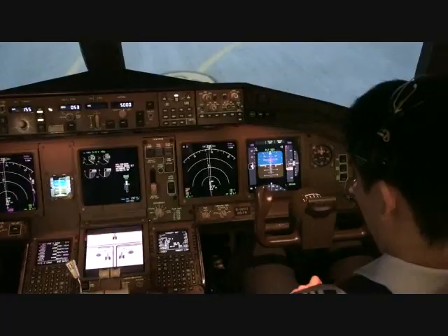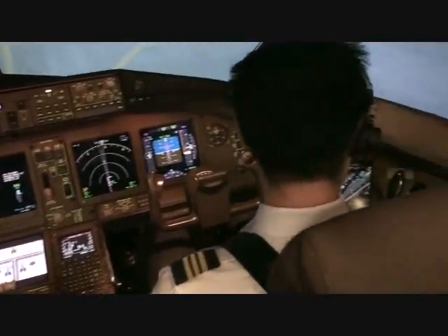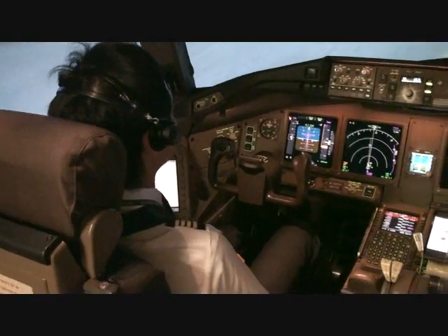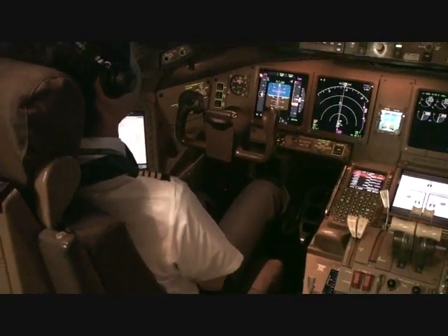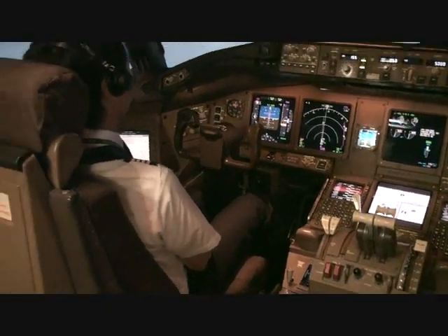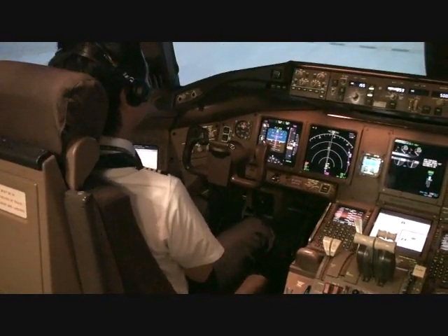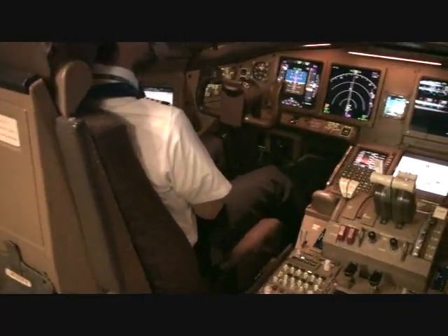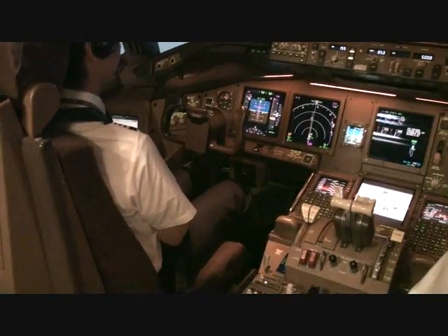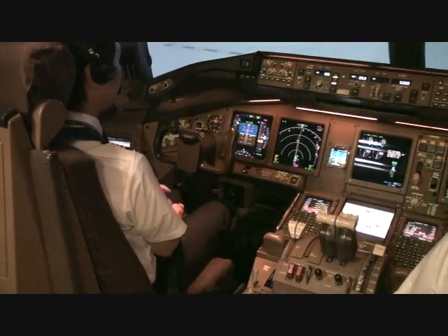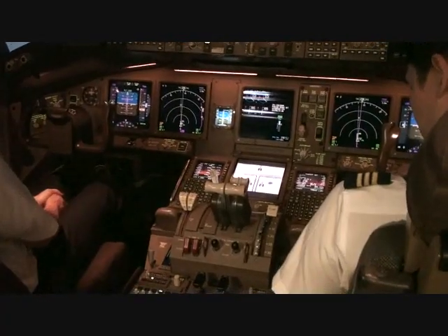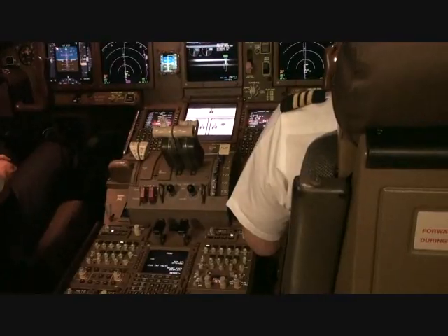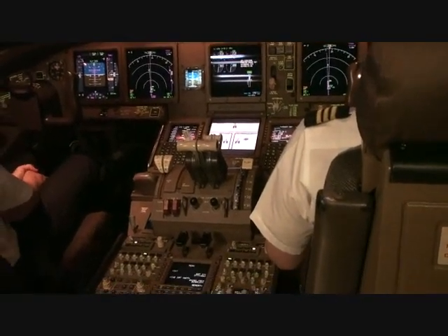Visually verify that the ground crew and equipment are cleared before the rudder check. CM1, hold the nose wheel tiller during the rudder check to prevent nose wheel movement. Move the rudder pedals to full travel in both directions and verify freedom of movement and that the rudder pedals return to center. If the transponder has not already been set to transponder, set it to the transponder position. If there was no pushback, the ATC transponder should be set to transponder immediately prior to taxi.